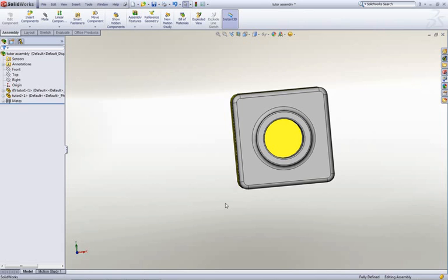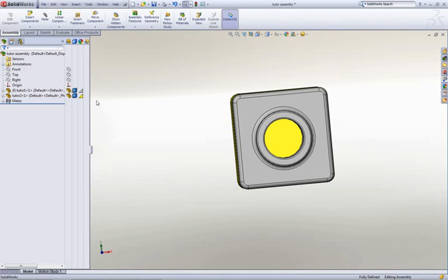The display settings for each component can be changed and saved. At the top of the Feature Manager design tree, click Show Display Pane. The display pane shows different display settings of each component. To add and save a display style, right-click in the display panel and select Add Display State. Enter the name you would like to give this display configuration and press Enter.